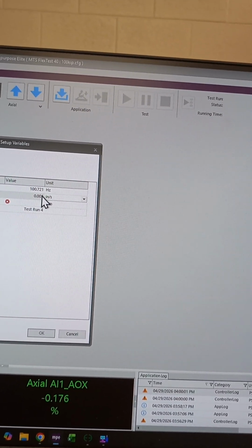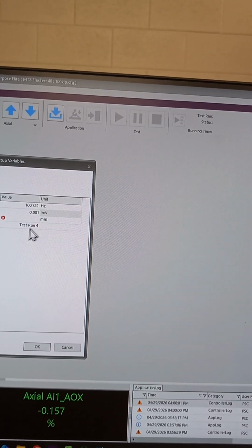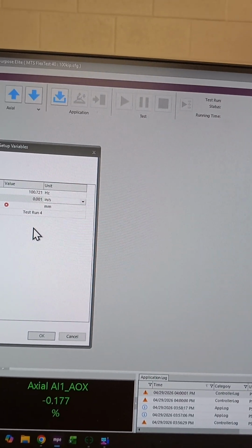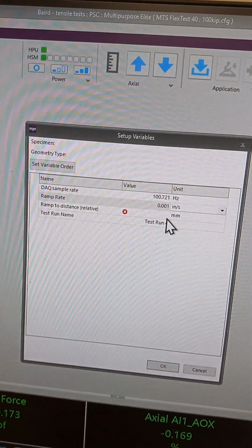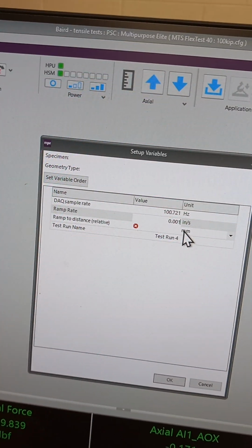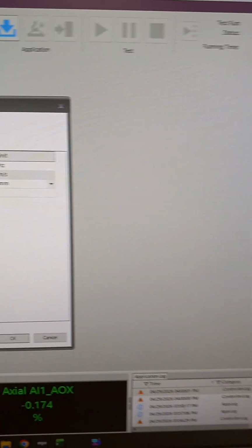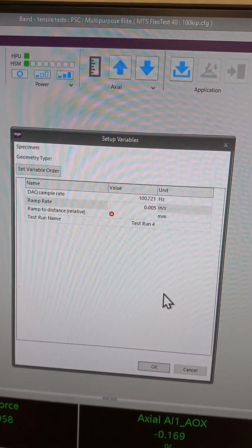I don't know. I'd err on the slow side because you can always go back and take data out. That's true. You can't put extra data in after you've taken it, but you can always take it out. Correct. So I would go probably 2,000ths of an inch. Although this is just plain aluminum, so let's go 5. On your samples, I wouldn't go faster than 2 for the first one. Okay, then 2.